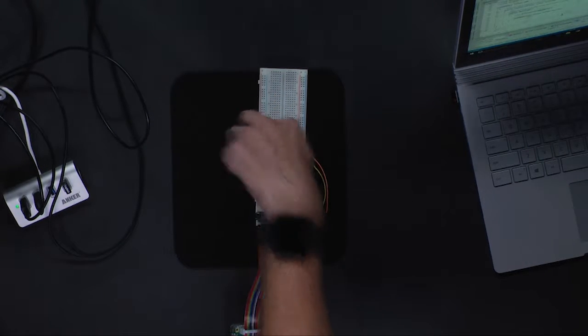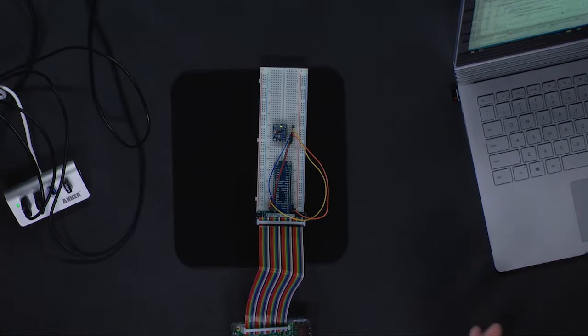Right here, this that I've pointed out a few times, is an accelerometer and gyroscope. So it makes sense that with an accelerometer and gyroscope, I can detect movement, right? I can detect twisting movement. That's where the accelerometer comes in. If you twist, I can detect it with gyroscopic speed, or if you move up and down, I can tell that you're moving up and down. That's the acceleration. But acceleration also gives us gravity, and that's actually how it's measured. So there's a bit of math involved here.